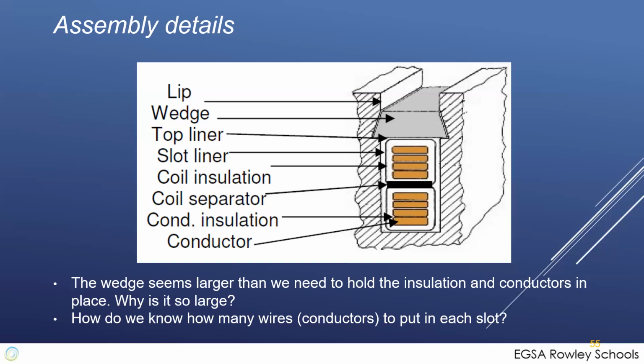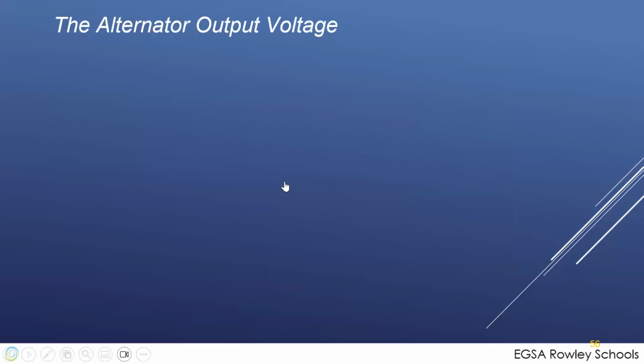So they're all tested, and to hold the windings in place, they're stitched very tightly with that polyester cord, and they're also wedged in place with these wedges to prevent them from moving. So it forces them to hold together in the event of a problem. Any questions on that part?